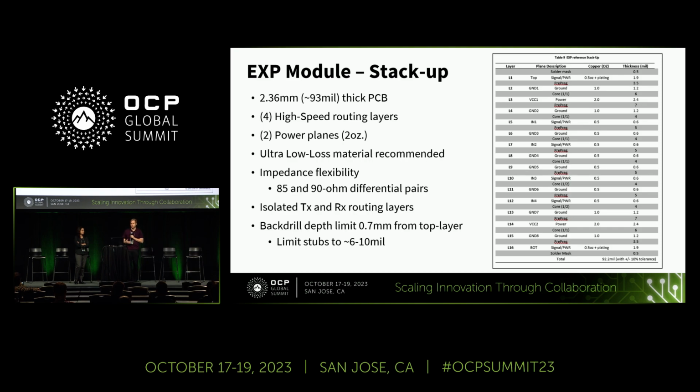One of the key things with respect to the pin map is how that fits into the stackup. In addition to the backplane style connector that's used to transmit the high-speed lanes, there's a Gen-Z 2C connector, and that connector has a defined thickness for the PCB. That set the limit for our PCB thickness and the number of layers we'd be able to get out of this module. We needed at least 4 high-speed routing layers. This helps us maintain the isolation between TX and RX. We also needed adequate power to support the 400 watts, but obviously for some applications we can do much lower than that.